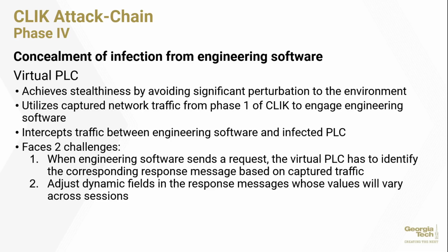Now, what that means really is when engineering software is communicating to the actual PLC, the virtual PLC is going to intercept that request, and based on some reconnaissance that it did in phase 1, it's going to pick the correct response message to send back to that engineering software to make it look like the normal PLC is talking to it just as it always has been.